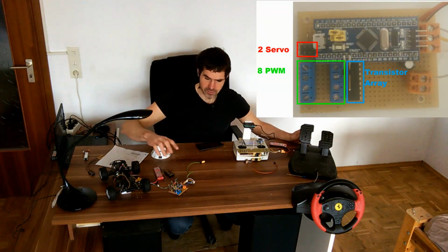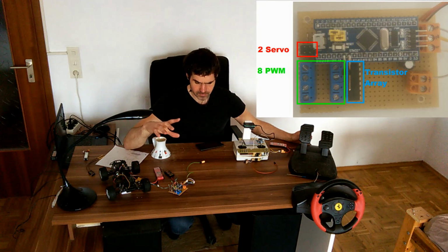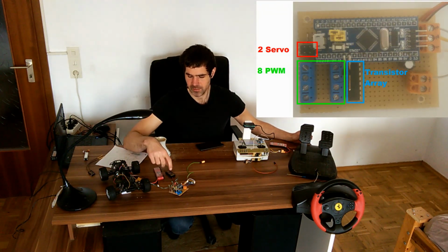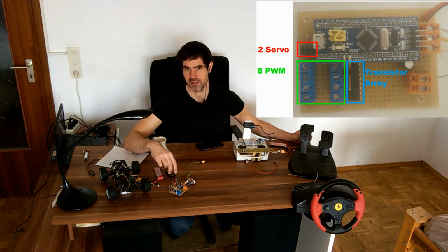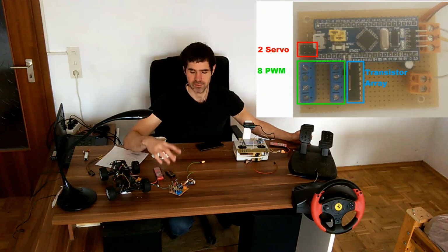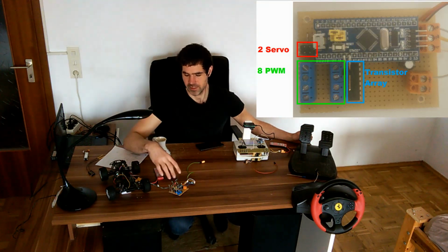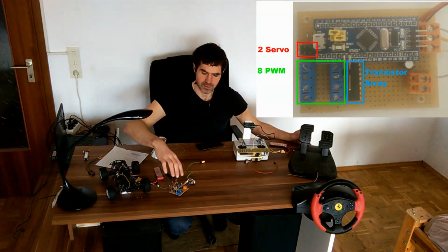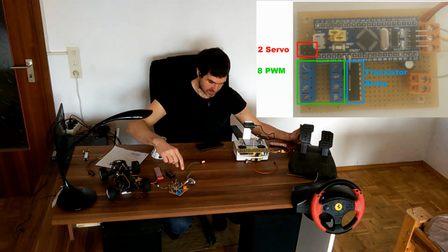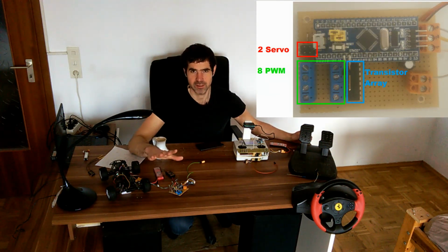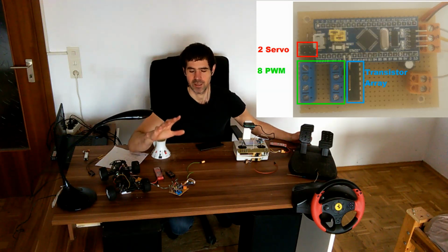And what this thing can do for me is it reads in the PPM signal I've been talking about from the receiver, so it only gets positive and negative in one signal wire, and on the signal wire all the information from each channel is bundled. So this signal is getting disassembled by the Arduino sketch in there, and then there are 10 pins which output a PWM signal.